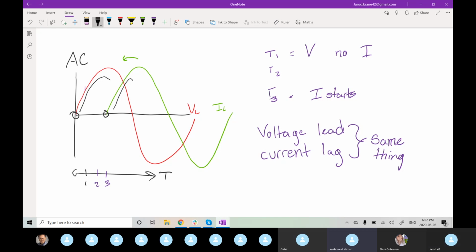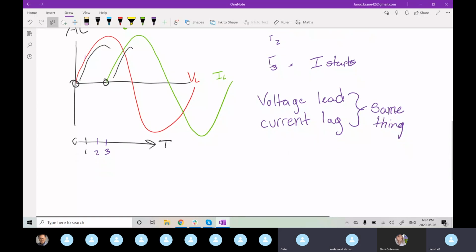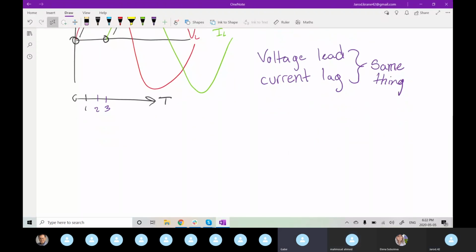But then when you put a lot of capacitors, could that cause the voltage to lead the current in a way that you don't want it to? Usually not in that application. More capacitance is helpful for those because you just have so much inductance that you're usually not to the other side where you have too much capacitance. Okay, cool. And your motor is also a huge inductive load because it's just coils of wire as well.